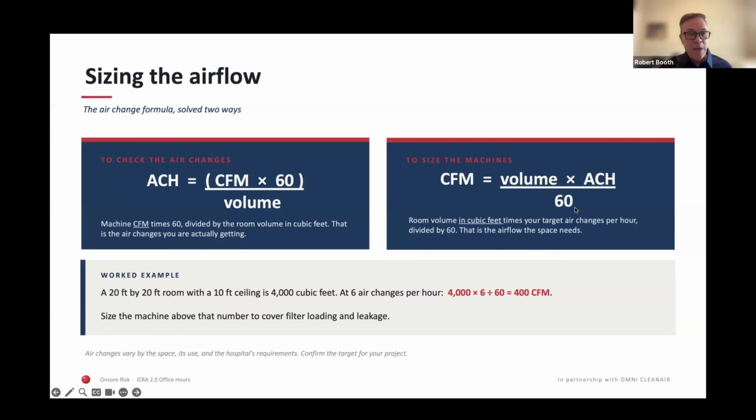wanted to mention is getting that negative pressurization in that room is affected by a number of things. And I just saw this at a facility a couple of weeks ago where they didn't close off the supply vents for that space. So they were getting a number of CFMs from cooling in that space that they had to overcome. So they could never really achieve negative air.